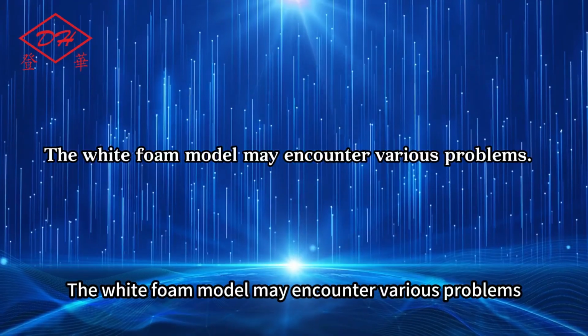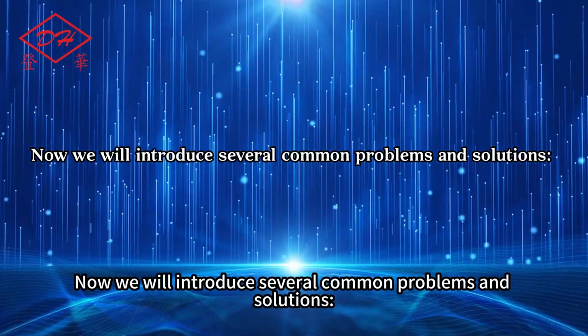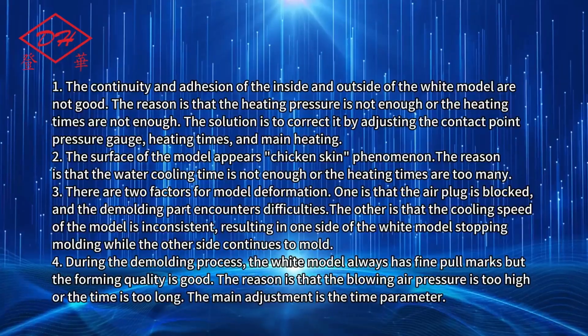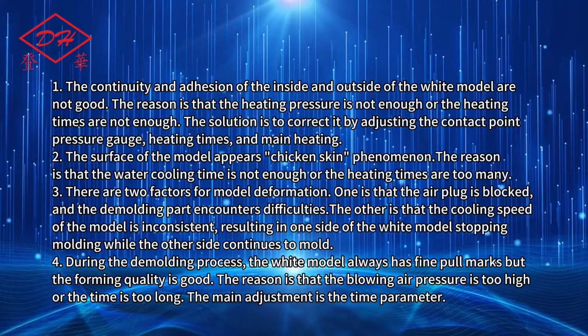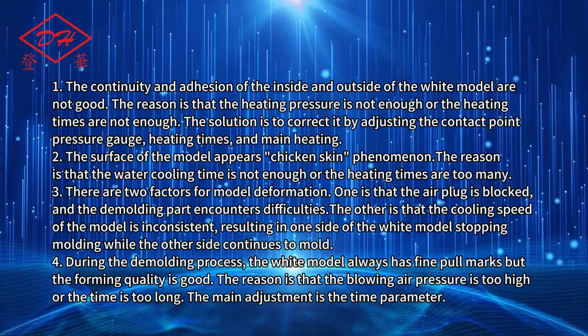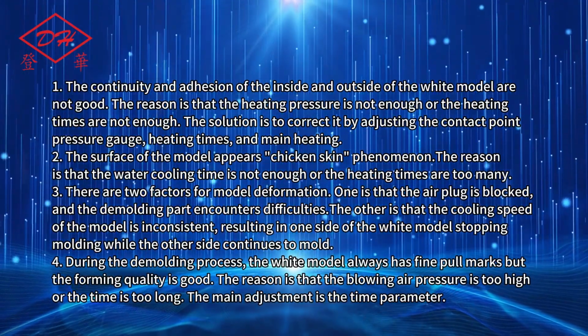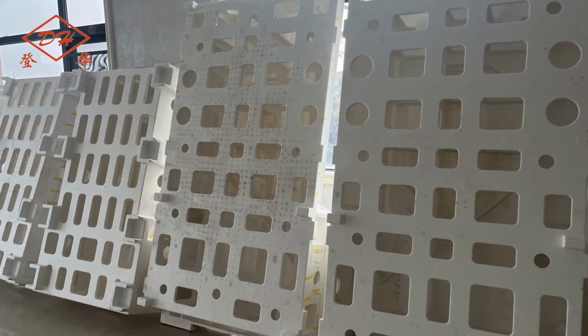The white foam model may encounter various problems. Now we will introduce several common problems and solutions. First, the continuity and adhesion of the inside and outside of the white model are not good. The reason is that the heating pressure is not enough, or the heating times are not enough. The solution is to correct it by adjusting the contact point pressure gauge, heating times, and main heating.